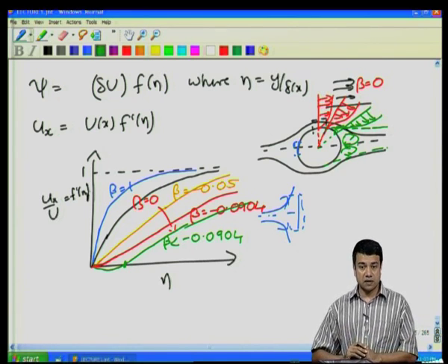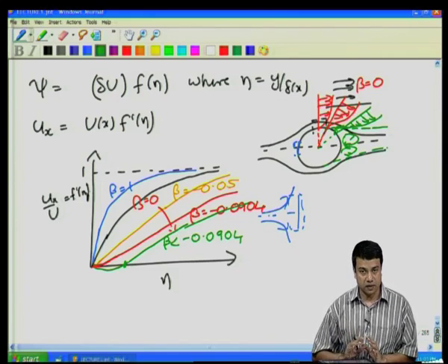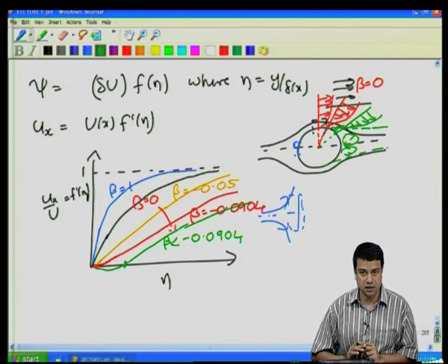So, even though the potential flow predicts that the velocity is symmetric, because the boundary layer separates on the decelerating side, you end up having a wake behind the cylinder. In this wake, vorticity effects are not small. The pressure within the wake is much smaller than the pressure in the potential flow, and for that reason you get a net force.